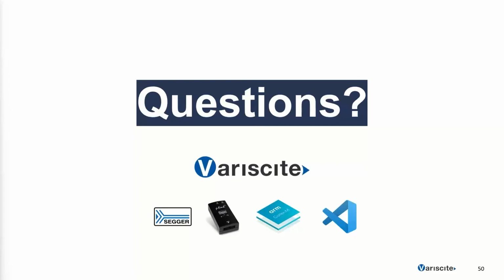Can we debug without J-Link? You can run the firmware without J-Link. So the first example that we walked through early on in the presentation, where we built it from the command line without using VS Code, we then ran the firmware using the Linux remote proc framework. You could do that, and I suppose you could debug using printfs or some GPIO pins or something of that nature. To actually debug and use breakpoints, to my knowledge, you have to use a J-Link.